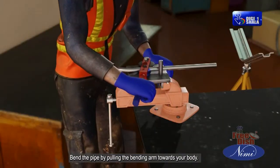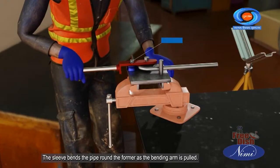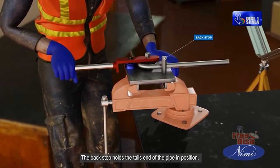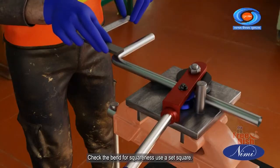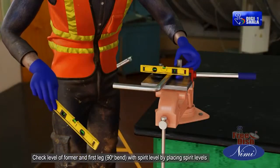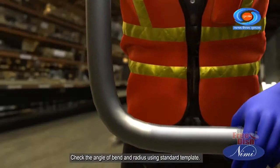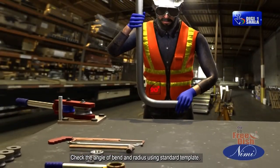Bend the pipe by pulling the bending arm towards your body. The sleeve bends the pipe round the former as the bending arm is pulled. The backstop holds the tail end of the pipe in position. Check the bend for squareness, using a set square. Check the level of the former and first leg of the 90-degree bend with a spirit level. Check the angle of bend and radius using a standard template.